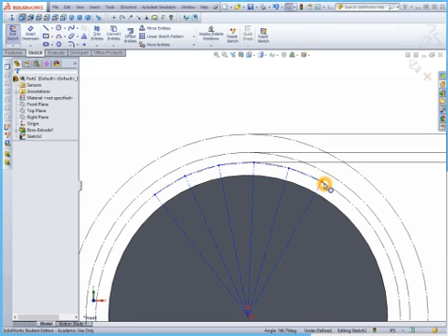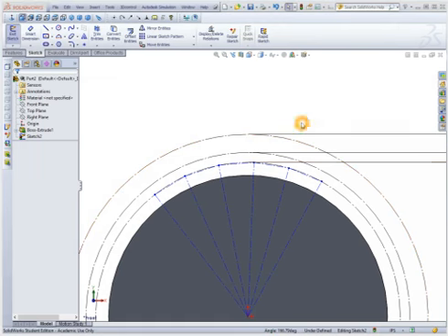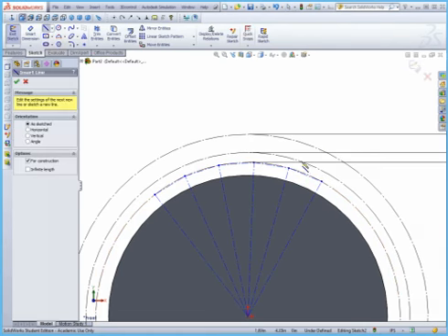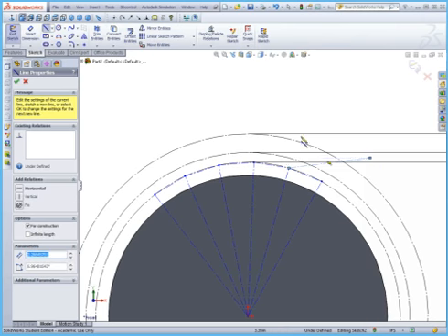So basically our spline is going to start at this point here, and it's going to work its way away from it and curl towards the left-hand side of your screen. And what defines the rate at which that spline turns to the left is going to be a variable radius curve. It's going to be based on the distances to the other segments. And so what we start doing here is drawing tangent line segments. Now I'm going to draw them arbitrarily at first, and then we'll make them tangent using relation.